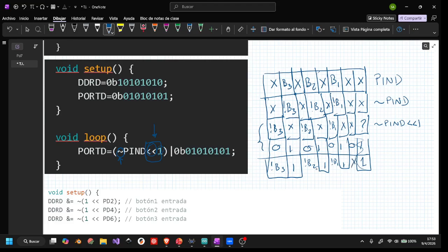So with this mask, the only thing that I am doing is maintaining here the pull-up resistor. That's the reason I select here 1, because I want to maintain my pull-ups. And the zeros let pass whatever value I generated before, right? That is the signal of the buttons inverted, right? And with that code, it should work, right? You are having the problem because you have here an AND, right? And you are multiplying by zeros and by 1. I think that's the reason it was flipped, right?